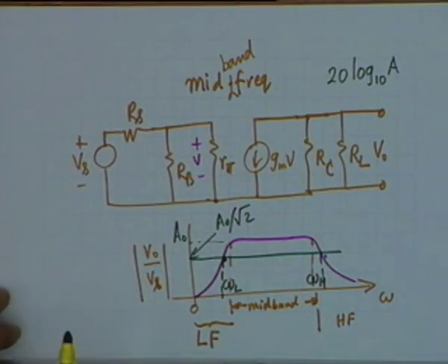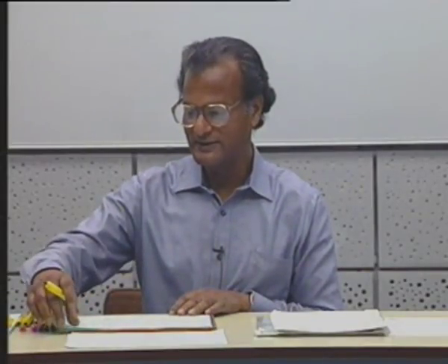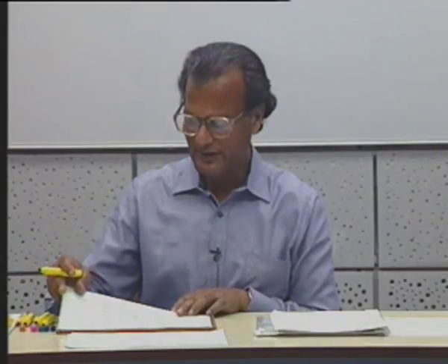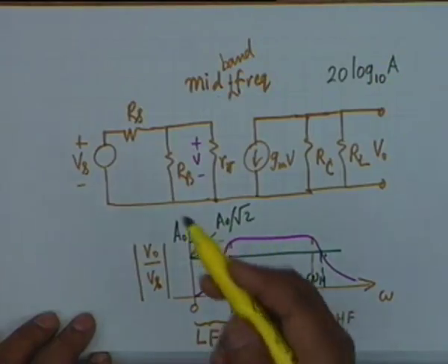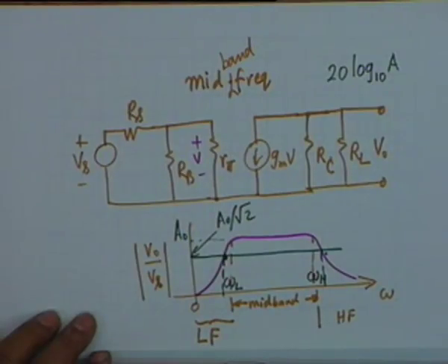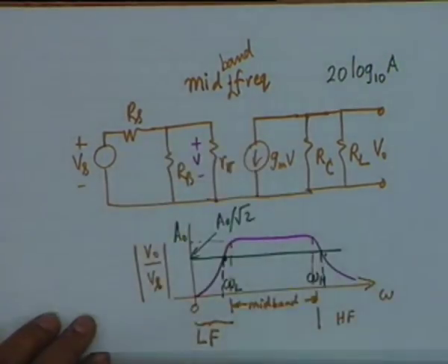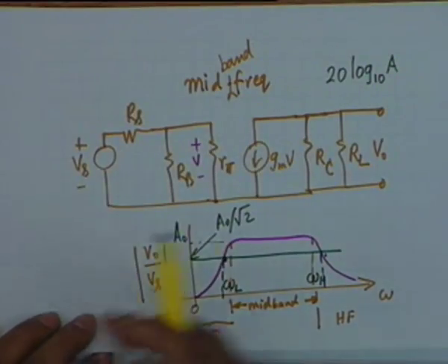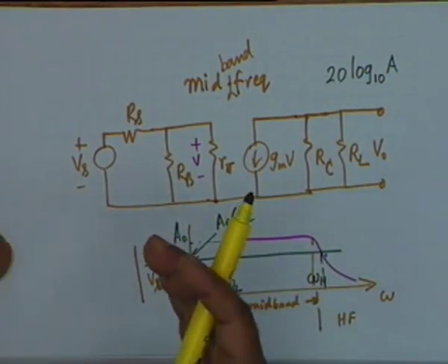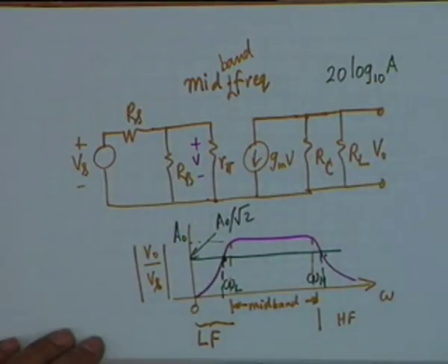Did I not discuss decibels earlier? Oh, I didn't. Okay. The gain, you see, could be a very large quantity. It may vary from 0 right up to, let us say, 10 to the 5 or 10 to the 6, and it is very difficult to represent such a large dynamic range, and therefore what you do is you compress the range by a logarithmic transformation.